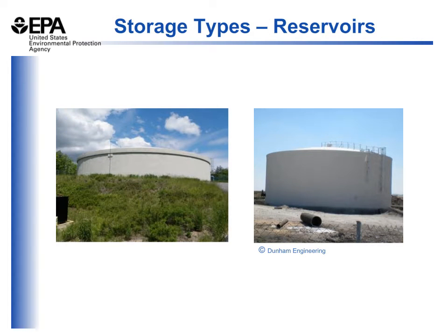Another type of storage tank is a reservoir. Those can be located both above or below ground and will typically have a lower construction cost than an elevated tank. One of the downsides to these tanks is that they require a pump station nearby because you're not getting that pressure advantage you would get with an elevated tank. An upside to these is they're less visible.